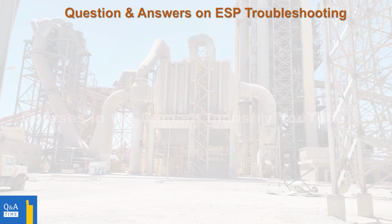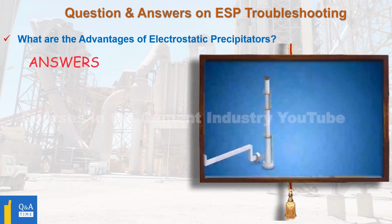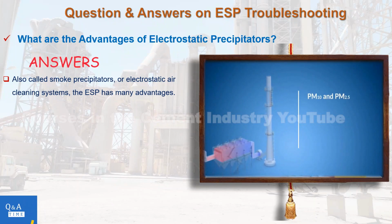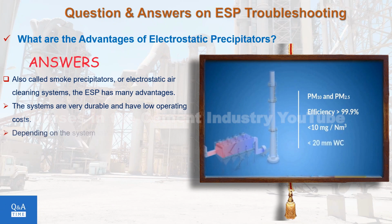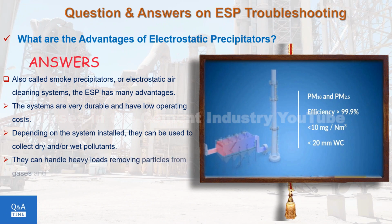Question 17. What are the advantages of electrostatic precipitators? Answer. Also called smoke precipitators or electrostatic air cleaning systems, electrostatic precipitators have many advantages. One. The systems are very durable and have low operating costs. Two. Depending on the system installed, they can be used to collect dry or wet pollutants. Three. They can handle heavy loads, removing particles from gases and dust. Four. High efficiency, 99% particle removal.